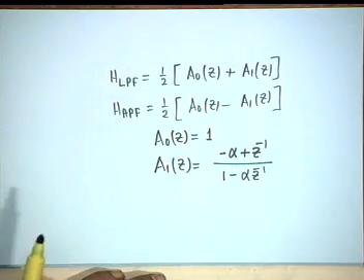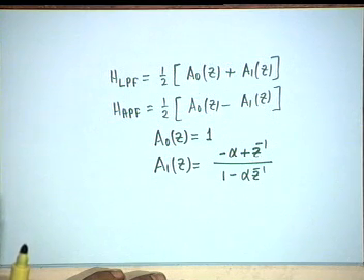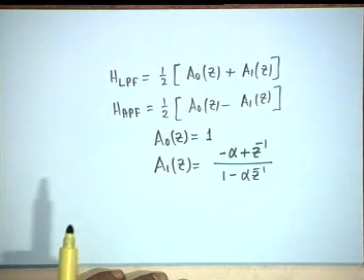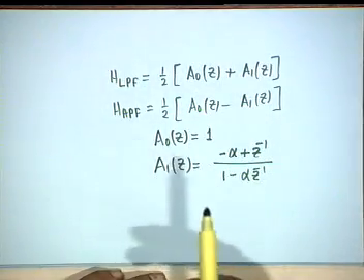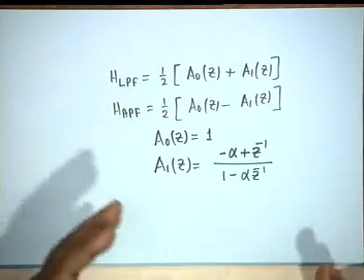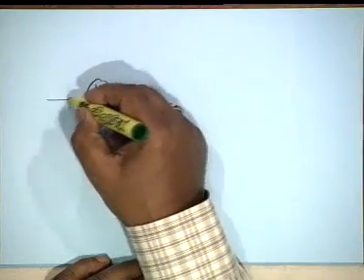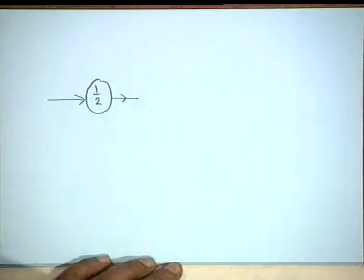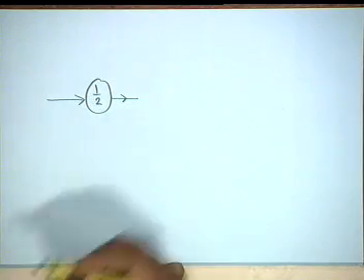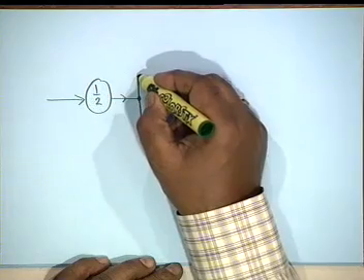One of the outputs is low pass and the other is high pass, and this is one of the most popular things in digital stereo. The low pass one goes to one channel and the other stereo channel is the high pass one. So, low frequencies and high frequencies are separated out, and that is what makes a stereo record. The implementation we also discussed earlier, because it is half sum and difference. So, we can realize the two filters like this, take the factor half out, which is a shift, no multiplication, and then you have two channels.